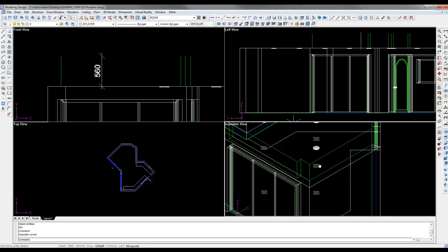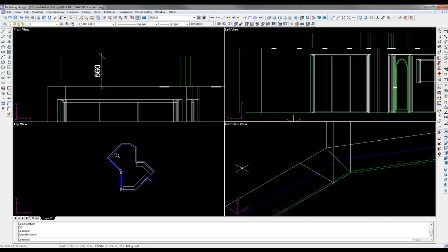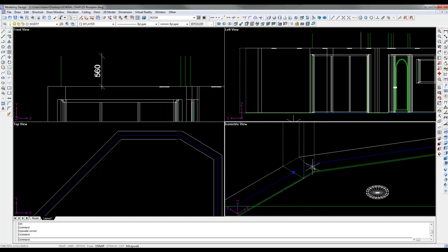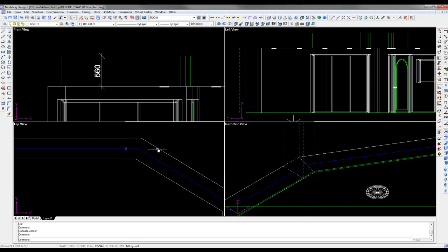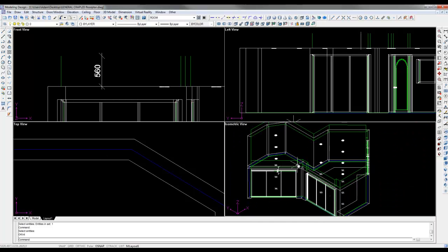And now what we're going to do is merge this through to the current scene. There's also a little bit of wall here that I want to try fix up because I'm not too happy with this little segment here either. So I'm just going to delete that. Okay. Then I can use the update function, which is this one here, just to fix those two edges up. And now we can use extend, I think, or trim. Let's try extend. So I'm going to select this wall first, right click, select the second wall, and then it neatly joins them up. Okay, so that's all good.